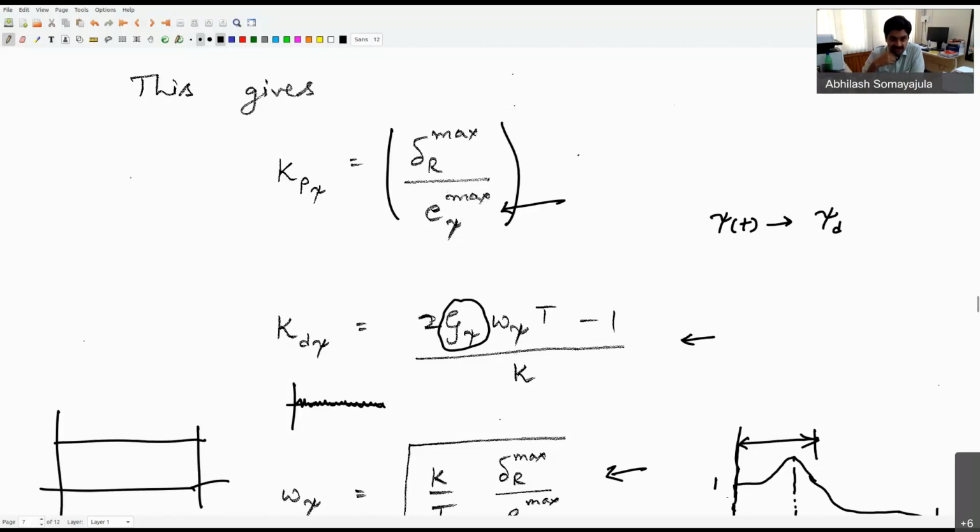So in essence, at the end of it, it will track my heading angle psi to my desired heading angle. Now that desired heading angle can be coming from one of the guidance laws which we have discussed before. So either a heading autopilot or a course autopilot can be specifying my desired heading angle, and we are now developing a control system which will try to track that desired heading angle. Everybody with me so far?